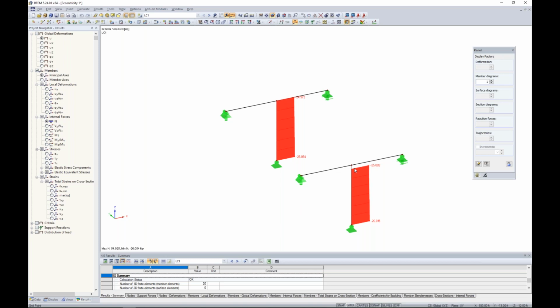So again, this isn't a BIM software. We're just truly here to do the analysis. Now the exception, well, we'll get into another exception in just a minute, but considering connection design. Of course, with connection design, you need to consider offsets and eccentricities when a beam is framing into the face of a column. That's clear. But when we're looking at overall member design, in so many scenarios, it's just really not necessary.